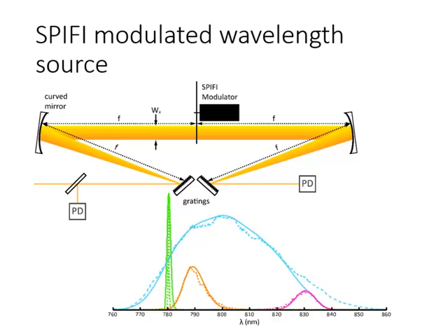And so this is just some test data taken on a Ti-sapphire oscillator, where the solid lines are this modulated single pixel spectrometer measurement, and the dashed lines are a commercial grating spectrometer. You can see pretty good agreement on the right-hand side here. This is very initial data because I didn't have the whole spectrum on the mask, so we lost some light there. But when we put some transmission filters here at 790 and at 830 into the beam, you could recover the filter's transmission function from this hyperspectral information. So that's all encoding information in a single spatial dimension.